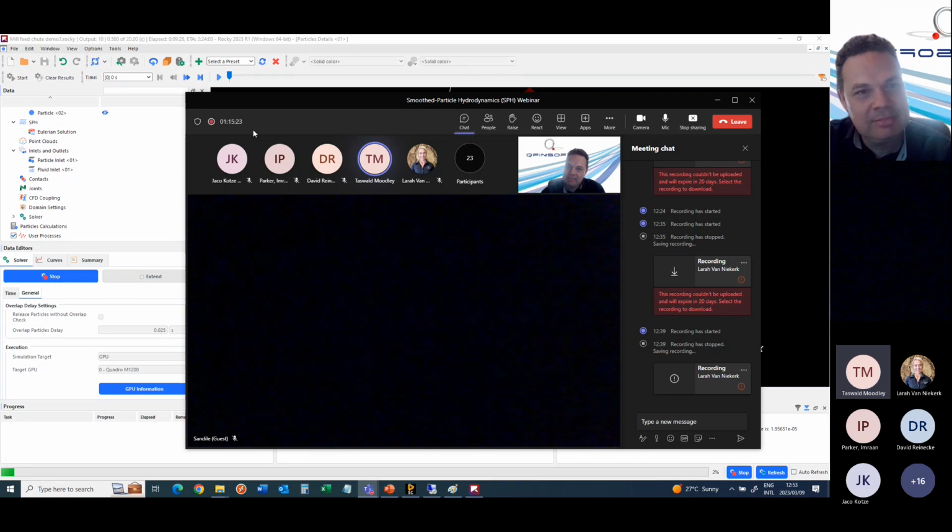But what I noticed is because it grows linearly, once the SPH particles hit the boundary wall, because they're growing at a very fast rate, then it stops filling. And that's your quote unquote fill. So I just wanted to know, am I doing something silly with the volumetric filling? Is there some toggle or something that I should try in order to get just the interstices between my particles filled?